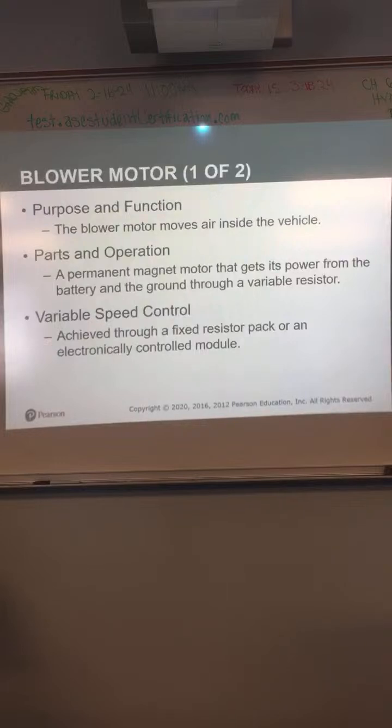You got hot or you got cold, or somewhere in between, but all it does is reverse the polarity and make it go one way and then the other way. Again, just like your window going up and down. You could think of up as hot and down as cold, but it works the same way. It only takes 2 wires to operate a motor, and if you switch the polarity on them, meaning positive and negative, the motor just turns the other way.